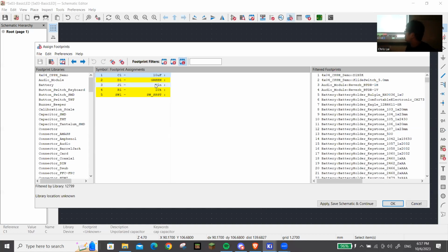Now, if you have no idea what the footprint looks like for your object, you can measure a capacitor or test it out or figure out exactly what size it is, because that's what's going to be physically located on the PCB. To help you with that, there's a lot of footprint libraries. The great thing about KiCAD compared to Altium is that there are a lot of default libraries already ready for you to start making your PCB. You don't have to go and find random components online.